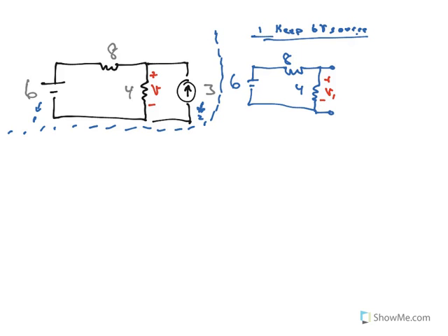All right, well, let's look at this circuit. Where this break is, over here, notice, let's say current is running through the circuit. The current's running through, it gets to this point over here, and it could either go this way to the right, or it could go down through this resistor. Well, notice it can't actually get to the right. It can't get over here. And the reason is because there's nowhere for the current to go once it reaches this break. Current can't flow through a break. There's nothing there. And so really, this break is as if that part of the circuit doesn't even exist.